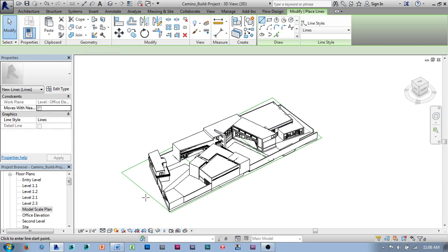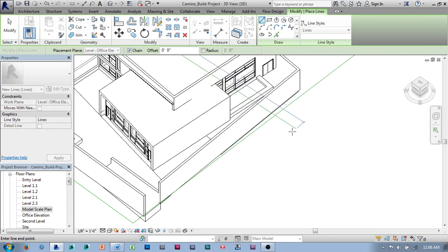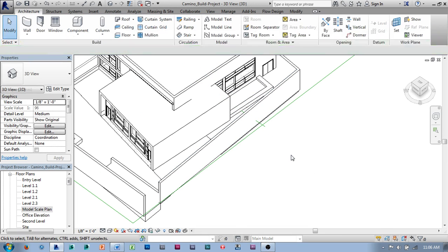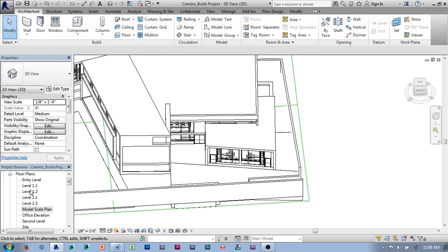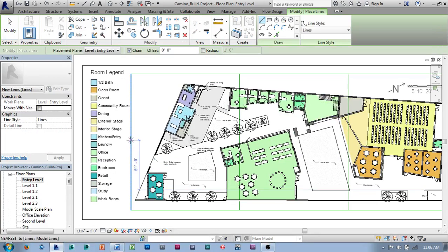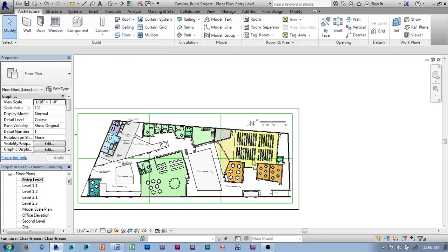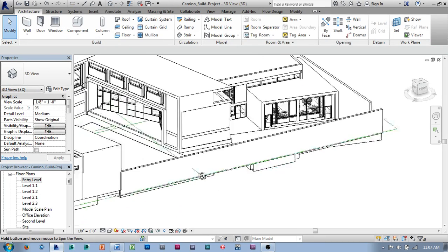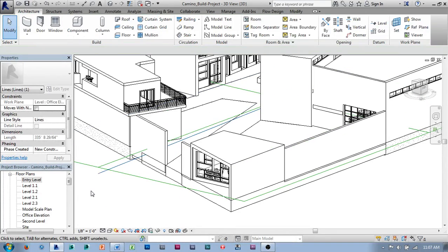Oh, looks like I'm missing one more line that needs to come through. Midpoint. To midpoint. And it doesn't look like I drew that in the exact same plane. Let's go back to entry-level drawing again here. Let's make sure I get that in the same spot. It put that line in a different reference plane, and I want to make sure that those things line up. So I should see two lines here, one below the other. There we go, get rid of that guy.